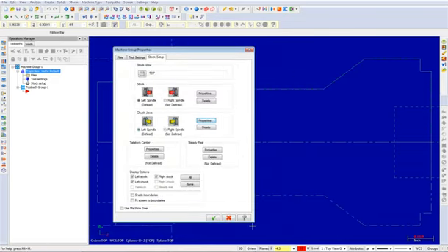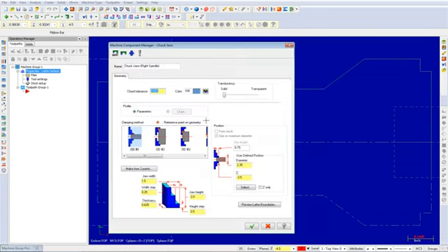Now enable the radio button in front of right spindle and click on the Properties button as shown. Pick the clamping method OD number 1 and disable the option From Stock. Under User Defined Position, input a diameter value of 2.55 and a Z value of 30. You can now select the OK button to exit the Chuck Jaws dialog box.